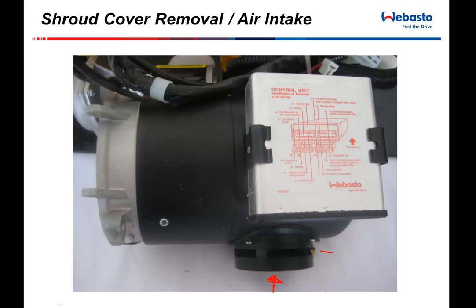There's a small set screw on it that would have to be loosened in order to open it. There'll also be a dot of paint where it was set from our factory. Over time, sometimes it is necessary, as there's wear and tear on the product and the fan gap in here starts to get a little bit longer, that you will have to readjust that,